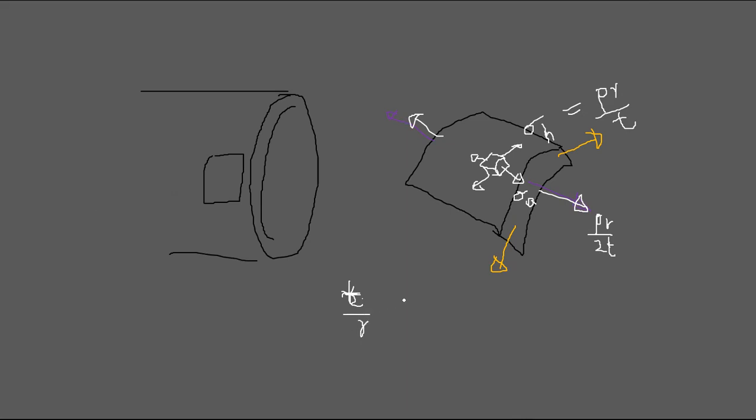There's some number; if it is less than that number, you can use this, because we are usually deriving this for thin walls, where we assume that through-thickness stresses are negligible.